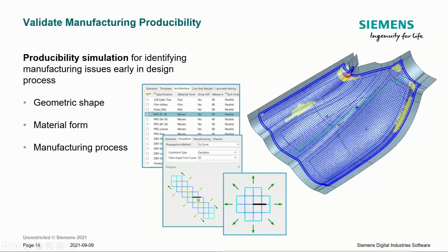We also have the ability to smooth along a curve or at a bias orientation. So when I show you the plies that go here for the 45, I can actually smooth it along the long axis of the part here, even though it's a 45 degree material. And that will be communicated not only from the design in Fibersim, we maintain the fiber rotation strategy, we communicate that with the analysis group, as well as onto manufacturing. You'll see these images on the ply book when we show the manufacturing illustrations.